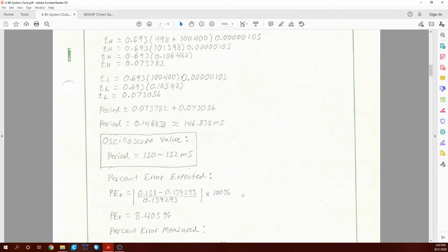And I'll tell you, one of the biggest things is because a capacitor never has the exact capacitance. It could be off by up to 20% in some cases, depending on the capacitor you're using. And that same thing for resistors. Some resistors are really good. They're only off by like 1% or even lower.